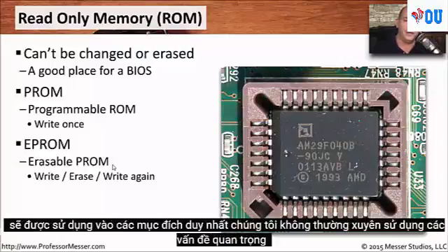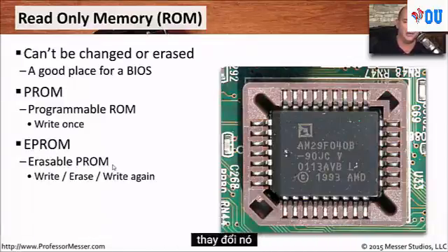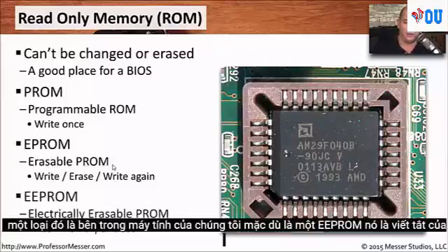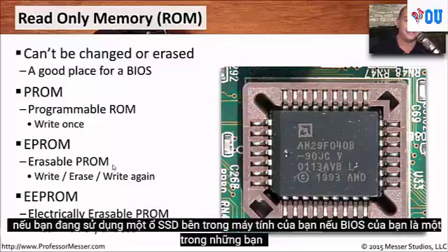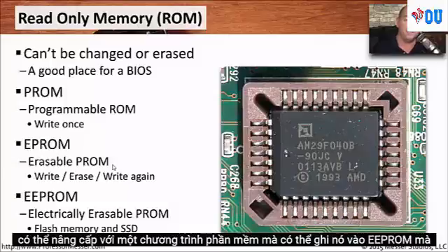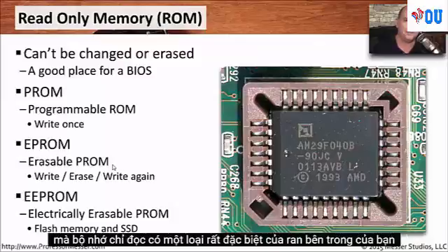Obviously, these would be used for very unique purposes. We don't often use these inside of our computers because we're not often pulling the ROM out and making changes to it. One type that is inside of our computer, though, is an EEPROM that stands for Electrically Erasable Programmable Read-Only Memory. So if you have flash memory, if you're using an SSD inside of your computer, if your BIOS is one that you can upgrade with a software program, it's probably writing it to EEPROM, which allows us at any time to electronically erase it and write anything else into that read-only memory.